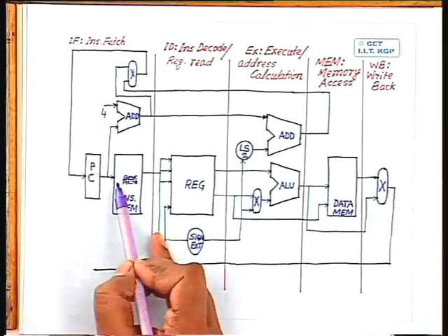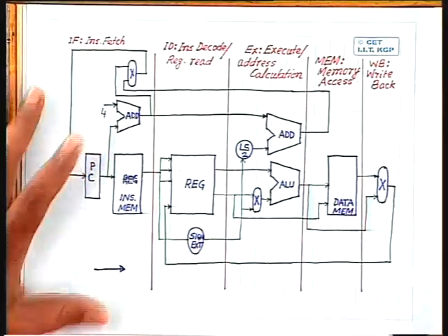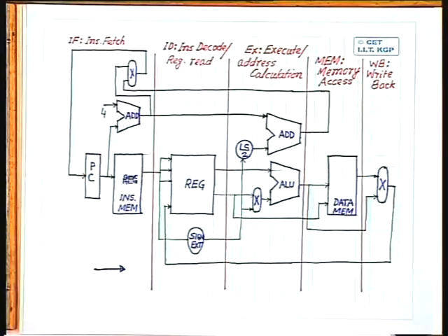If in the earlier case the branch was taken, you assume that the branch will be taken. If in the earlier case the branch was not taken, again you assume that the branch will not be taken. Accordingly, you select which instruction next has to come to the IF stage. However, these are all finer refinements, and obviously in this case you need an extra amount of memory to maintain the history. So there are advantages and disadvantages in every approach.